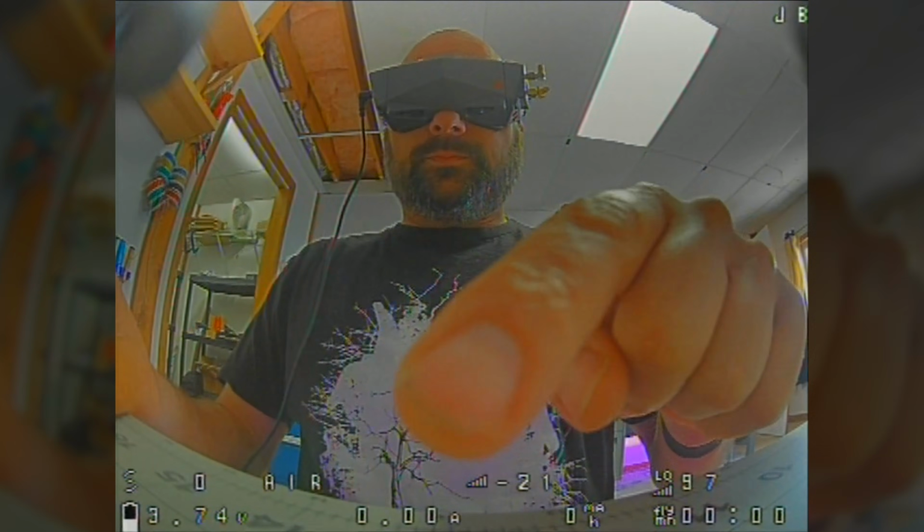What even is telemetry? I kind of skipped that. Telemetry is the ability of the flight controller to send data back to the controller that you're holding in your hands. Some people confuse telemetry with OSD data, on-screen display, which is information you see in the goggles. But in general, the OSD data is drawn on there by the flight controller or the video transmitter and isn't really sent back to the controller. It's just displayed in the video feed.